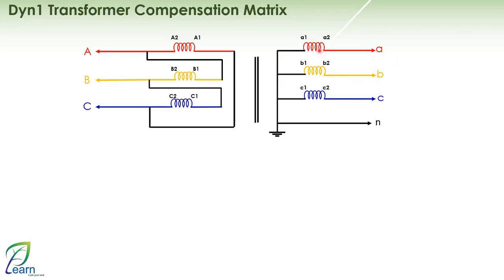If we assume the presence of an external single-phase fault on phase A on the star side, it will draw current in this manner. Consequently, it will draw a corresponding current from the delta side, also from the winding of phase A. However, due to the fact that your vector group equals 1, the external terminal connections cause the currents to now be drawn from phase A in the cables or the external circuit, relative to the transformer. This means they enter the winding of phase A and return again through the cable of phase C, so the currents will be in this manner.